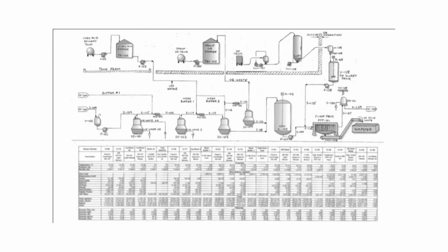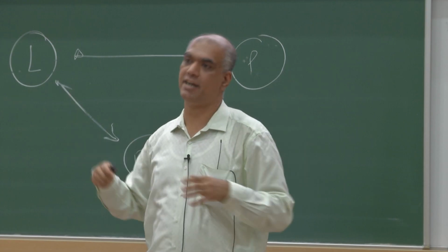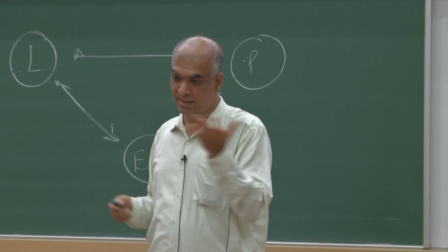Don't forget, sometimes you have a two-phase stream. Then you need to show how much of the phase is vapor, how much of it is liquid, what pressures, temperatures, what are trace elements, right? That happens in the table on the bottom, but see how well laid out it is. Because you can see the equipment, there'll be numbers for the streams, and those are in the table. So take some effort, but that's the difference between just a standard project and a good project.